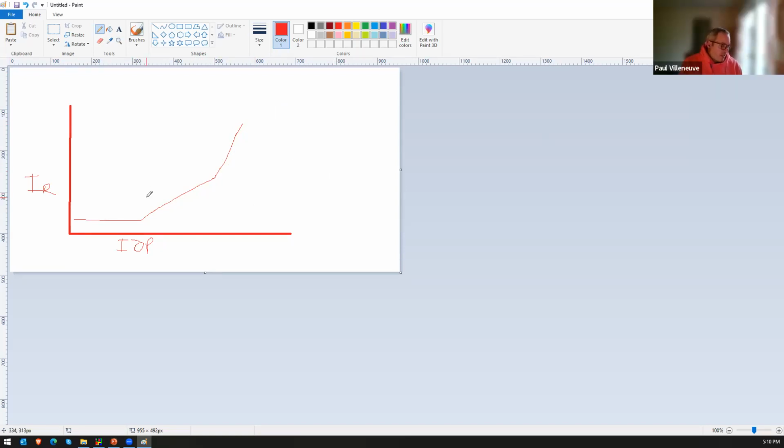So normally the test engineer will just plug in points that the settings engineer will say, here you go, plug these in, and it's either going to operate or it's going to restrain. And that just makes sure that the relay is doing what it's supposed to. It won't take care of the phase shift necessarily, but those are some of the test points that you have to develop. Yeah, that's exactly right.